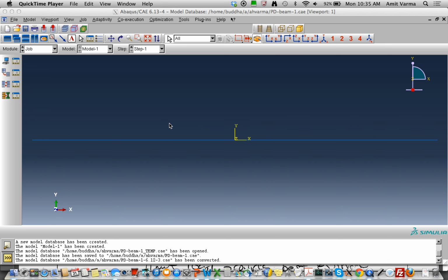So here, of course, we did the elastic analysis. We found where the first plastic hinge occurs. We introduce that hinge, then do an incremental analysis, as you're seeing here, and we go through all of this. We keep incrementing the response until I get two plastic hinges. Then again, we introduce those hinges and continue with our incremental elastic analysis. At the end of the analysis, we end up with a bending moment diagram that has got MP at 3 different locations, and we've got the overall behavior.